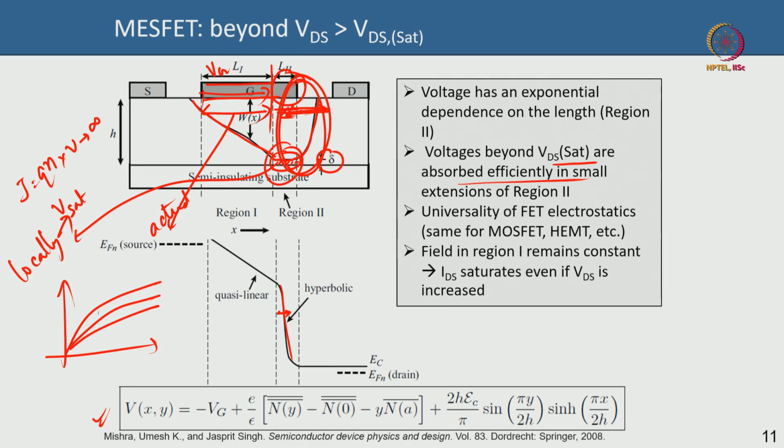Also, we should keep in mind that the channel thickness literally does not go to 0 when the drain pinch off happens. There is a small opening, because velocity saturation has a limit, so the carrier density available to carry current is also limited. You cannot make it 0 and expect the velocity to be infinite. This is all assuming the gate voltage is at a certain bias such that the channel exists below the gate. The drain is merely pinching it off, but the channel exists below the gate.